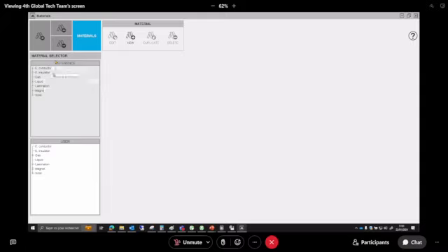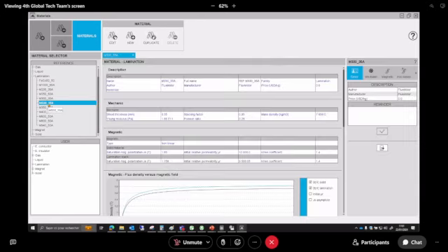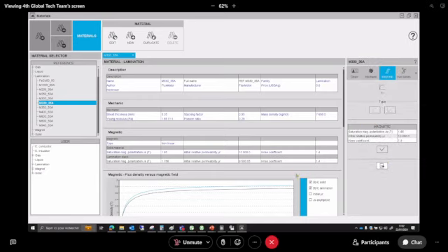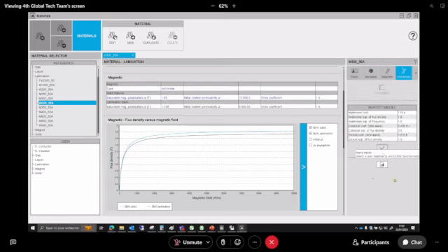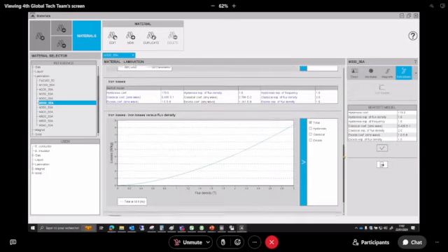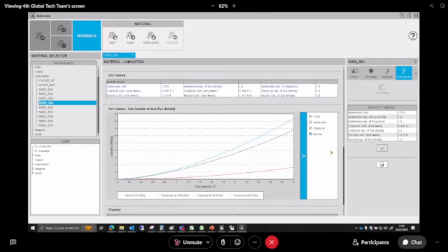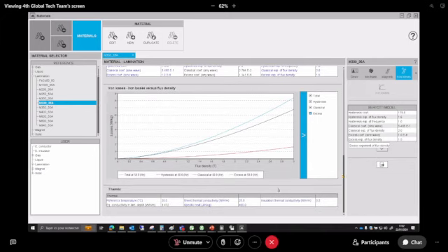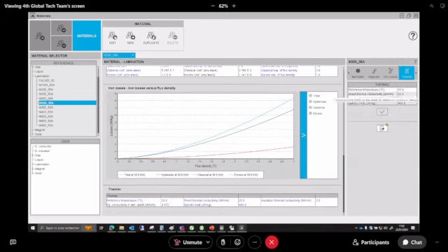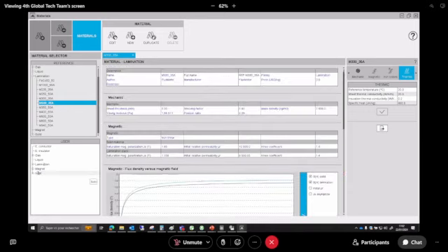So these few materials for the lamination are here, but if you have the characteristics that we need, for mechanics, because we are going to make some NVH analysis, for magnetic, mainly the BH curve and the losses, measured losses to extract the Bertotti model and the different components, so mainly the coefficients of the Bertotti model, and the thermal characteristics, thermal conductivity of this motor lamination, then you can create it directly here.